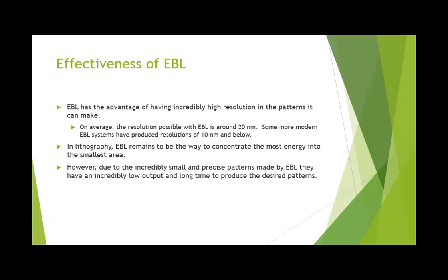But there's a lot of problems with it as well, which I'll discuss briefly in just a minute. But the big thing right now is cost. It's pretty expensive to be running basically scanning electron microscopes just to make shapes and patterns in little resists. And it also takes a really long time because it is such a high resolution, high fidelity process. It takes a super long time, so it's just not incredibly efficient.